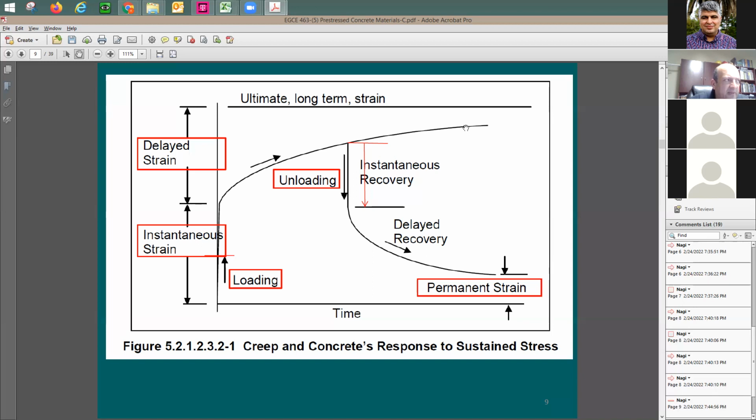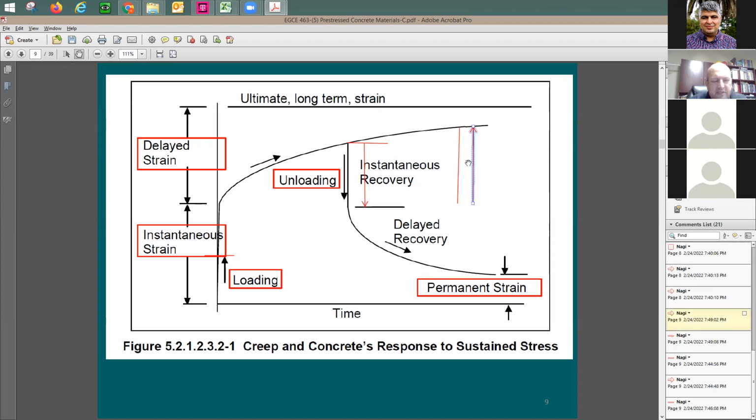It's going to be growing up, right? And then at the end, you're going to leave it or undo the loading, take out the stresses, right? And then it's going to be coming down like this. If this is just a straight line, it becomes, let's say, this way. And then this curve is going to be repeated. So the curve is going to be doing this. If this makes sense to you. So if you never unload it, the strain will stay high. If you never unload it, it's going to do this. It's going to just continue to a certain point.